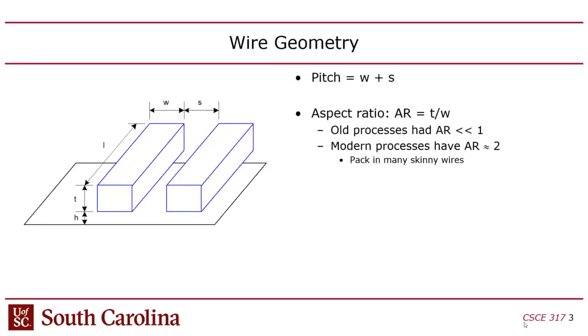Okay, so the wires are literally just wires. They're metal that runs across the surface of one of several routing layers or interconnect layers on a chip. They're above the substrate and the active layers where the transistors live. The objective is to have these wires have minimal resistance, and one way that semiconductor fabrication companies achieve that is by making the wires very thick.